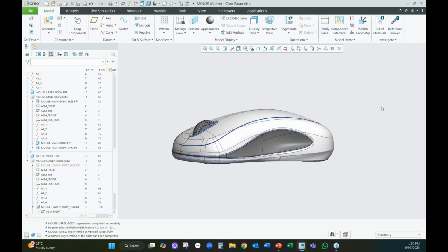In terms of setting up an assembly structure like this, I start with PowerPoint, and I just work with orbs, so I assign my part numbers, and I start to really map out, similar to what Ben was showing earlier in the slides, the different parts and which ones are going to be in assemblies, which ones are going to be in assemblies with skeletons, so sub-assemblies with sub-assembly skeletons, and map out the parts that way. One advantage is you've got your part numbers assigned with your names to your parts, so when you're creating the parts, it's a copy and paste exercise, but I'm always working with that end goal in mind of what I want this to look like.